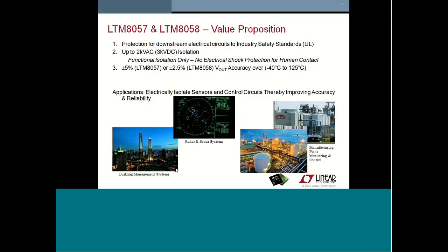Long power and ground wires could otherwise cause distortional measurement due to voltage drop and noise coupling. The building's infrastructure may respond as a result incorrectly. Other buildings, like industrial buildings, may need accurate monitoring and control to stay within environmental emission limits, or may have pre-negotiated contracts with utilities to limit their power consumption at certain points.